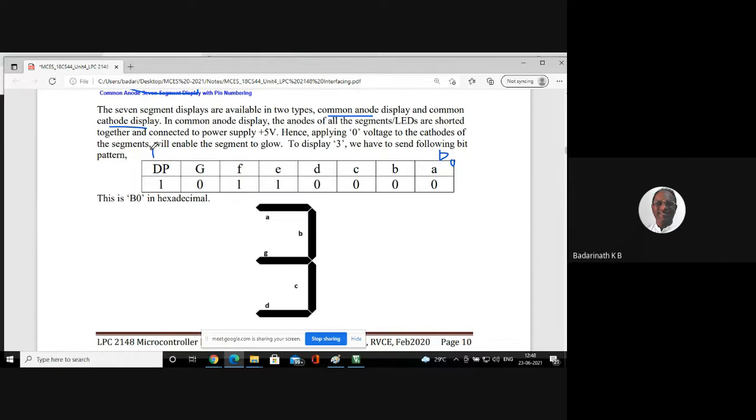When I am interfacing a microcontroller to the 7 segment, I do it in order generally. That means bit 0 always controls the first pin of the 7 segment digit, and the last bit always controls the last segment. We follow an order. So now I have written that order: A, B, C, D, E, F, G, and decimal point. Now 3 has to display.